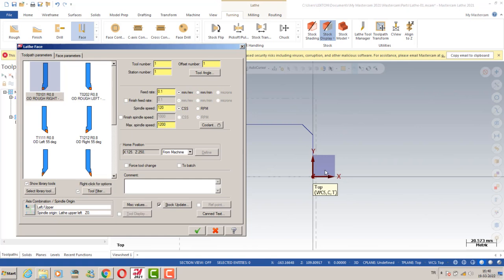So we don't want that kind of stuff here. So that's why I need to write maximum spindle speed here. This is 1000 and 100, 1000 and 300. Okay, so this is my feed rate, and this is my maximum spindle speed, and this is gonna be my constant cutting speed, and my spindle speed gonna calculate it automatically here. Okay, this is actually first step.